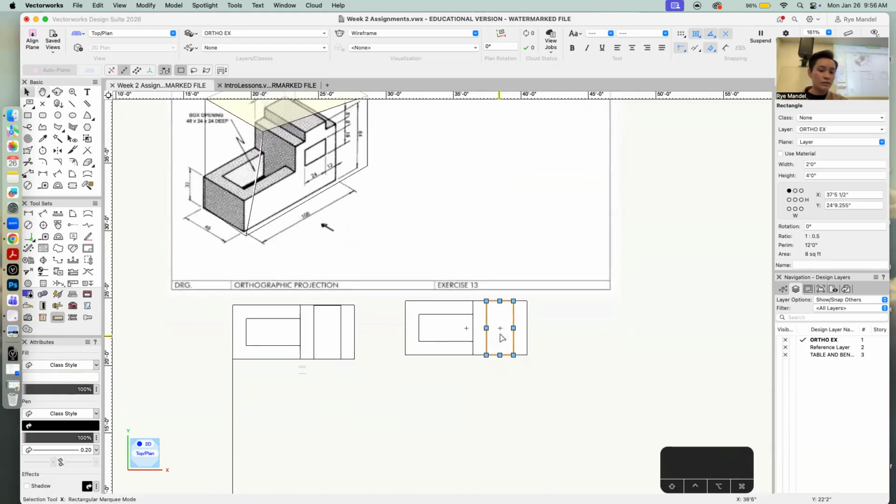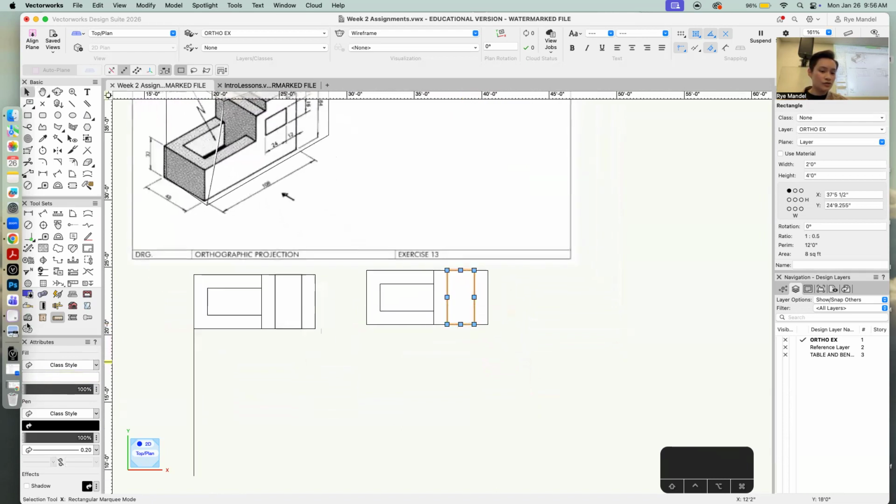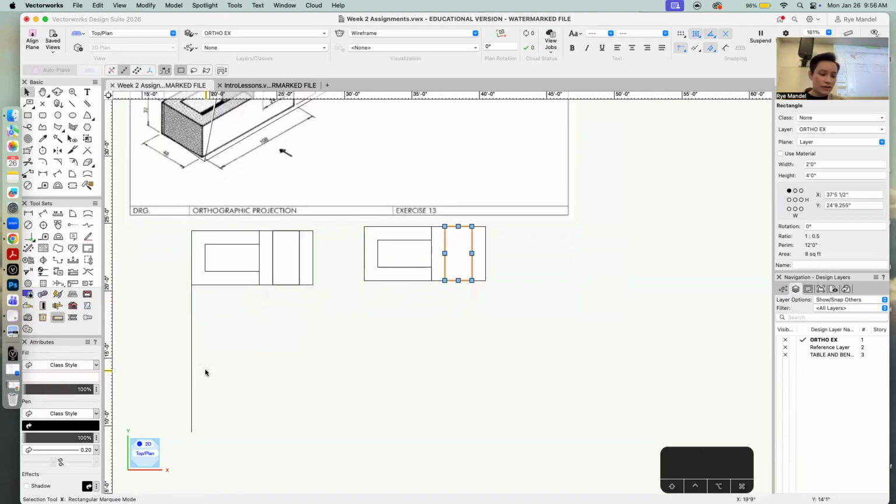Okay, so I'm going to change this to look like you're looking down and it's coming at you. The more it comes at you, the thicker the line weight. So with line weights, I want to go under my pens, and I can change it by going to my attributes. Totally valid way to do this.